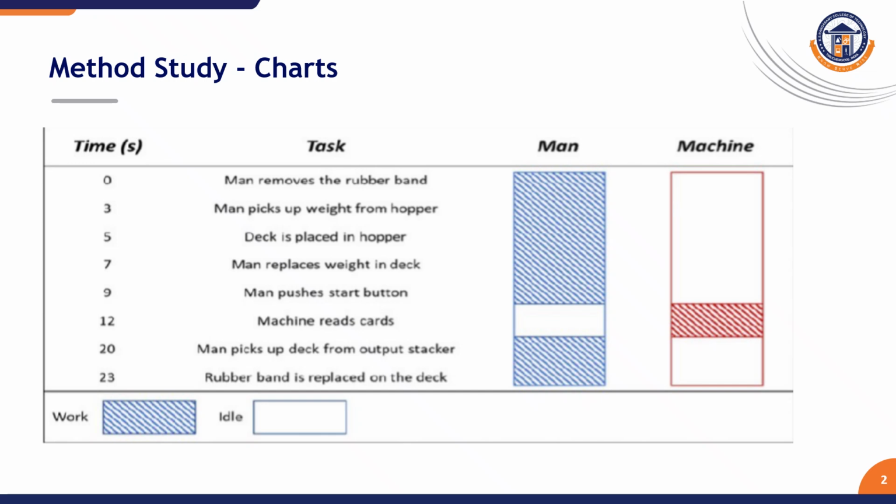Assuming it is a slightly automatic loom, you can give four machines. Now with the latest technology, rapier looms, air-jet and projectile looms, we can give up to 12 machines per operator. But in India they have successfully given up to six, I'm saying in medium scale industries. I'm not talking about corporates, but in corporates we can give around 12 machines. How this was done is they found out that during the manufacturing time the operator was idle, and to utilize that time, they allocated more machines. That is what has happened.